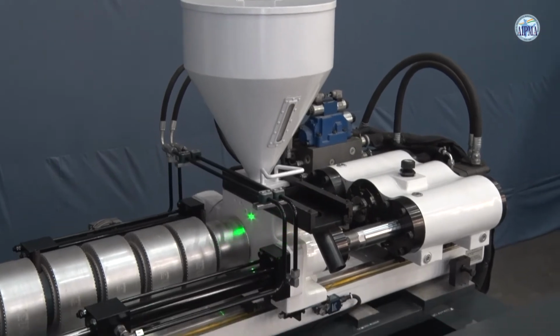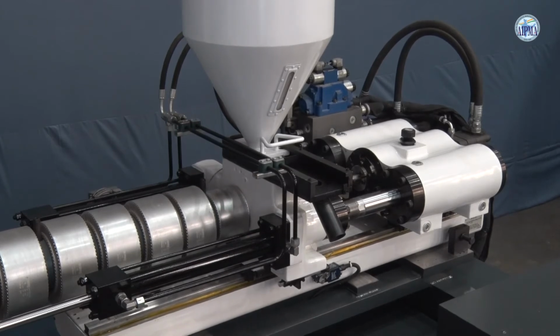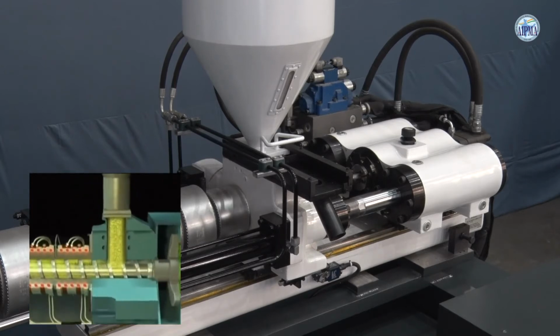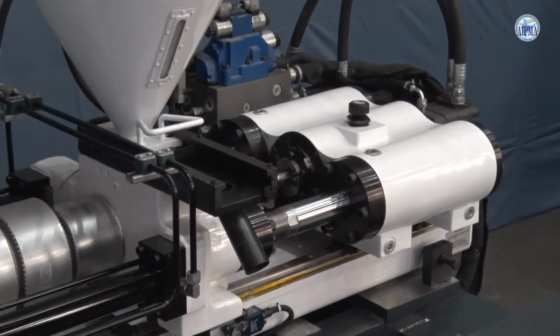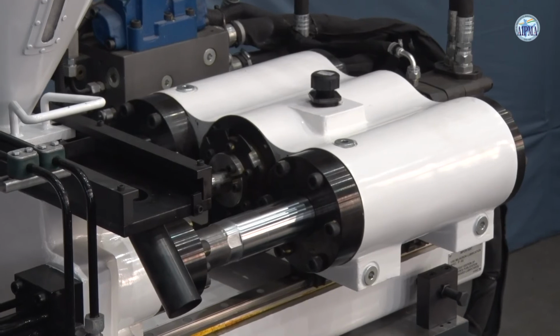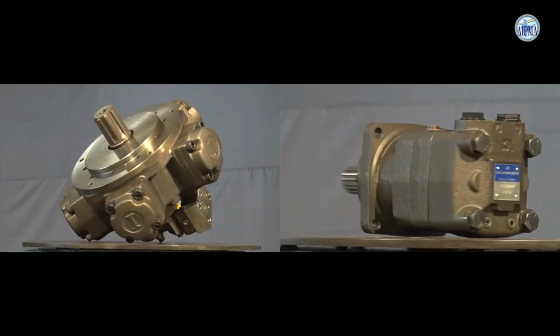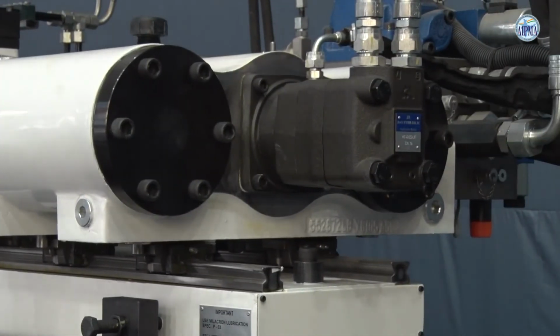Feed throat platen. Feed throat platen holds the barrel. Hopper assembly and injection cylinder are anchored on it. It contains a pathway that allows material from the hopper to feed down into the barrel. Injection cylinders. These cylinders are used to move the injection platen forward and backward, which in turn moves the injection screw forward and backward. Two different types of injection cylinders are used: integral and external. Extruder motor. This is a hydraulic or electric motor which rotates feed screw during refilling cycle.